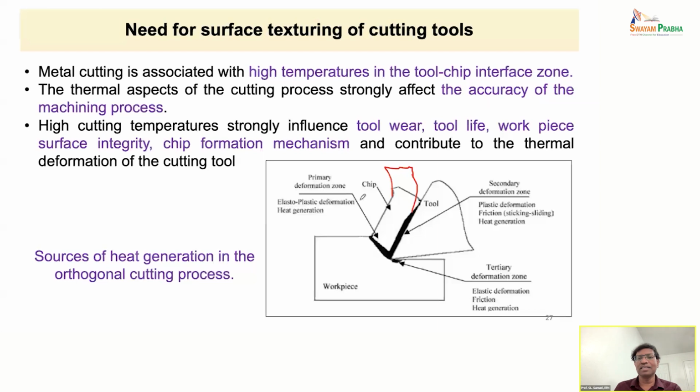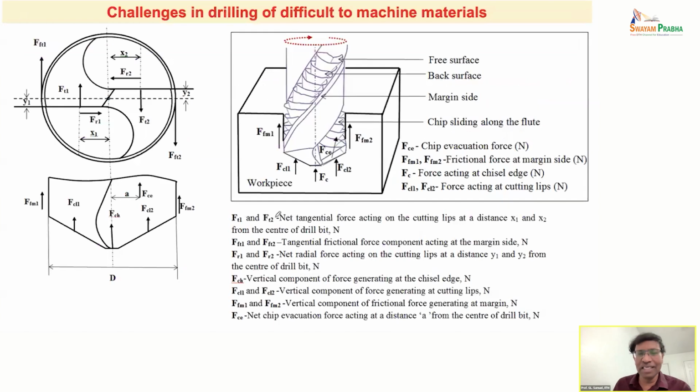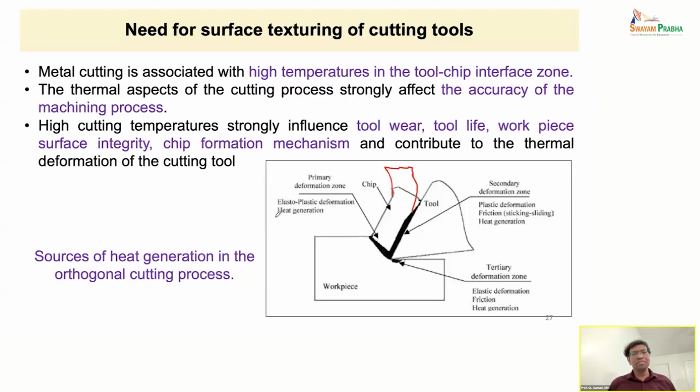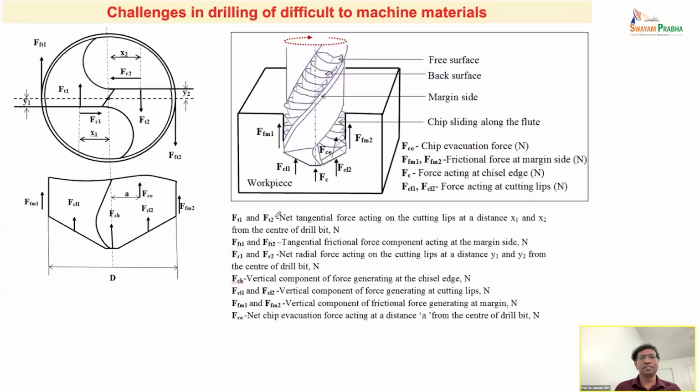At these places, heat gets generated. There will be friction and then there will be heat, as the metal is making contact with the tool. So friction plays an important role. When the friction is there, the heat gets generated, which is not good for the tool life. Also, if you are machining some materials like aluminum, built up edges will form. That means the material will soften and get welded to the tool. That's called BUE, built up edges.